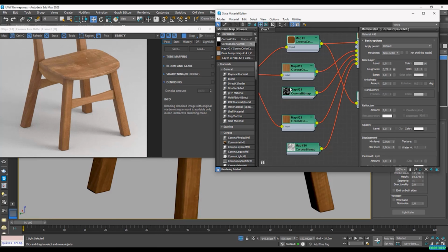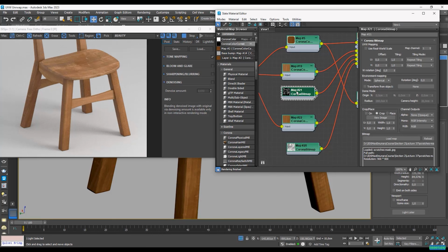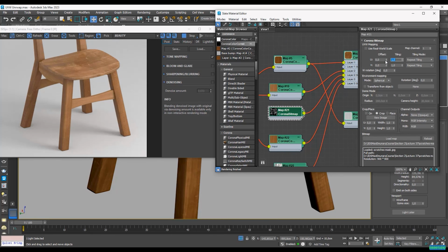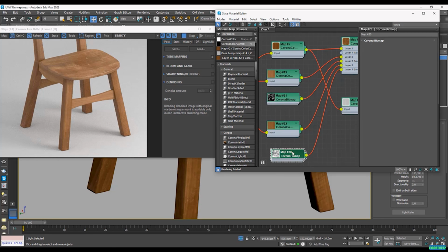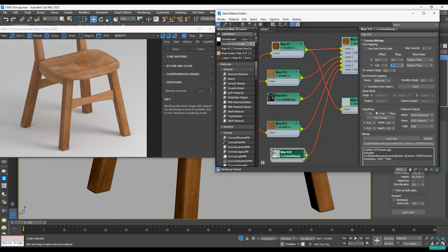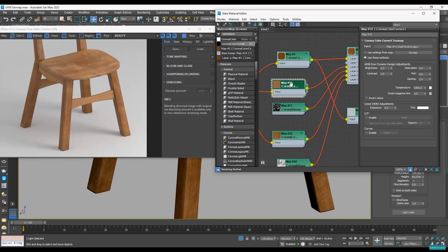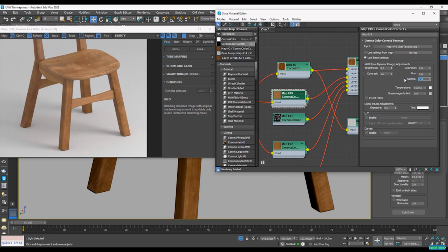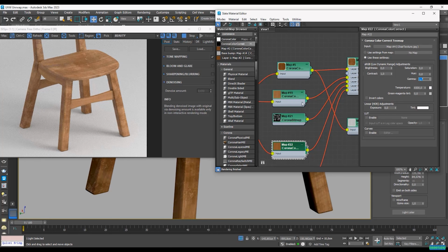So in this case, what we need to do is just add a bit more tiling to our masks. So I'm going to go ahead and type in a 3x3 in this case, and also a 3x3 on this one over here. Now let's lighten up some of our material here to bring these imperfections up a bit. So let's go for 2, and this one would have 1.7. Something of this sort will do. This is a bit too pronounced. Let's go for a 1.3 again, or again 1.5 should do it.